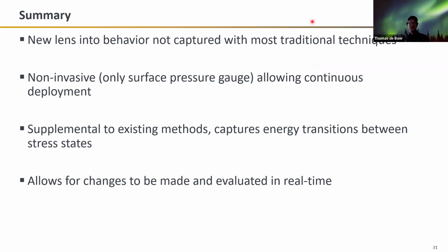In summary, what I presented here presents a new lens into behavior that's not often captured with most traditional techniques. It's non-invasive, so we're only looking at surface pressure gauges, and it allows for continuous deployment. It's supplemental to our existing methods, so we have strong integrations with microseismic providers, assessing that data as it comes in. And it helps us capture those energy transitions between stress states rather than focusing on post-stage analysis or post-pad analysis. And the critical thing here is this allows us to make changes in real time and to evaluate the impact of those changes in real time.